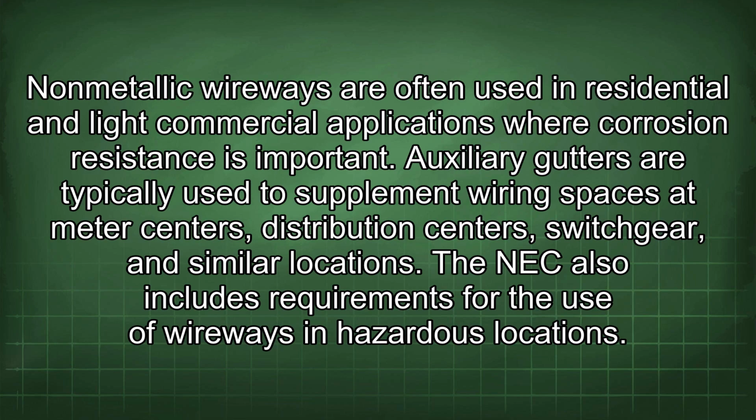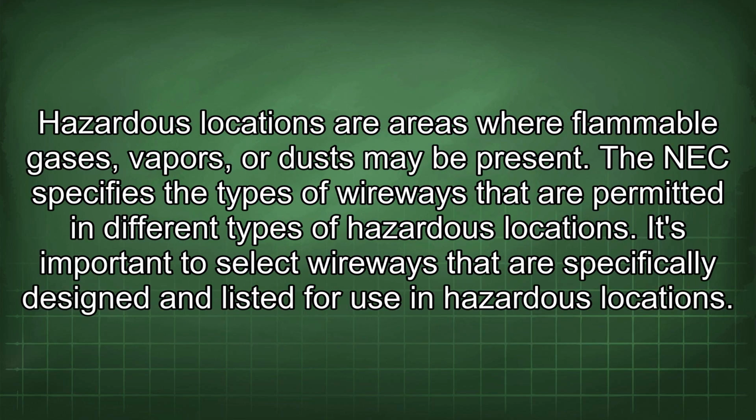The NEC also includes requirements for the use of wireways in hazardous locations. Hazardous locations are areas where flammable gases, vapors, or dust may be present. The NEC specifies the types of wireways that are permitted in different types of hazardous locations. It's important to select wireways that are specifically designed and listed for use in hazardous locations.